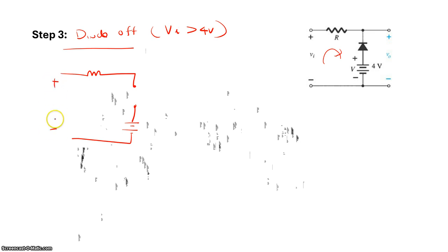This is going to be your input voltage Vi. You are taking your output across this, and we know that there is no current here. So the output voltage is just directly the voltage applied as the input voltage Vi appearing across the output.